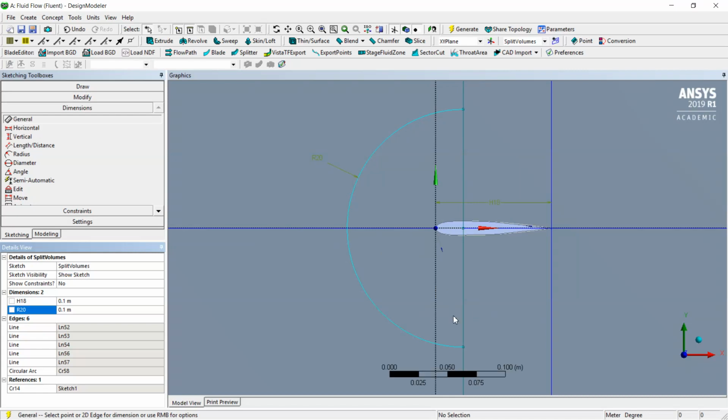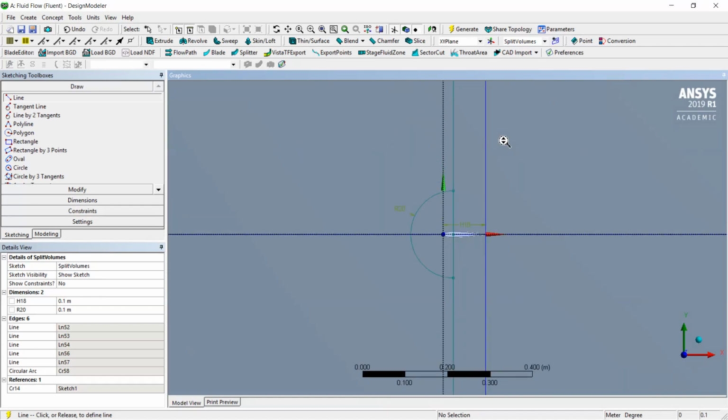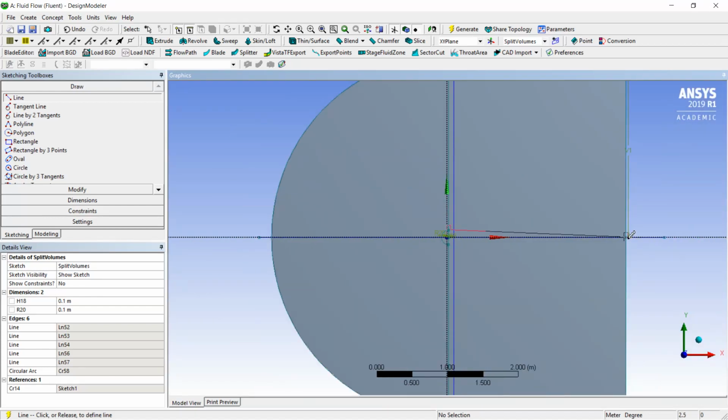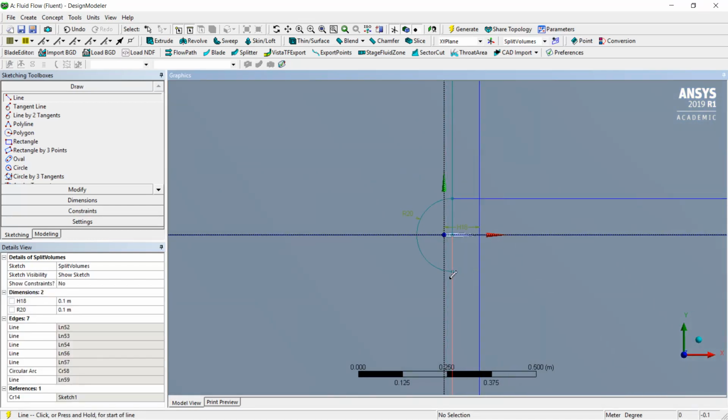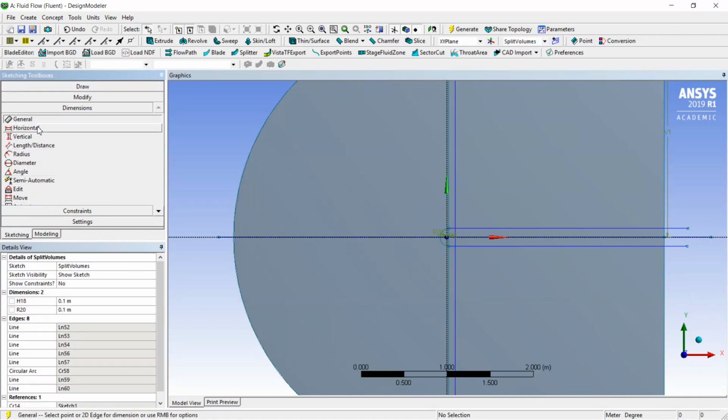so it's one chord. This is a volume near the airfoil, we have to mesh separately to have a good accuracy near the airfoil. And also I put the horizontal line like this and like this, long rectangular volumes here. They are formed for the precise simulation of the boundary layer separation from our model.